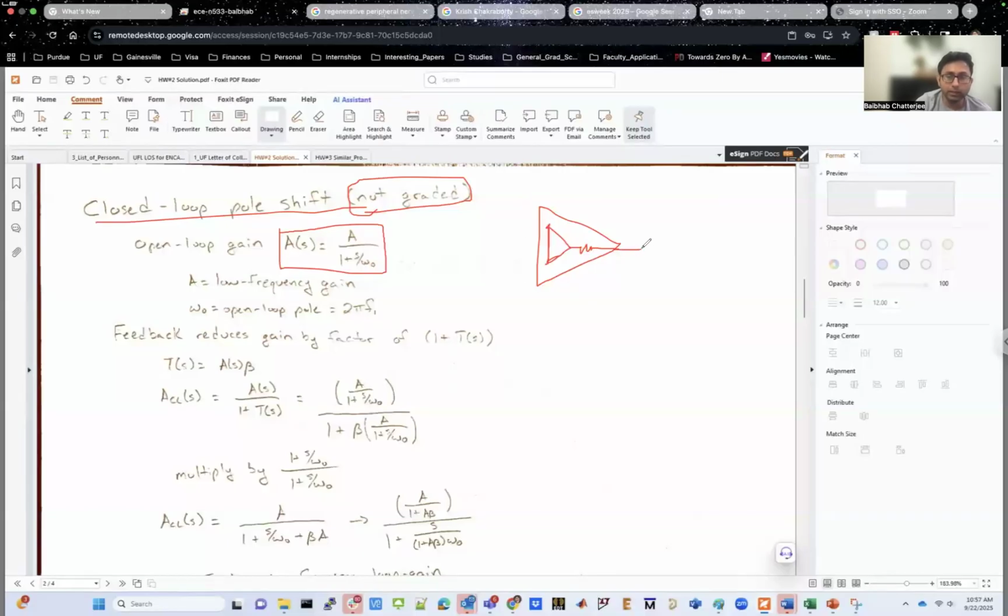So you have a resistance. And then, of course, for any circuit, at any point, you'll have a capacitance to ground. That's just the nature of circuits, that you always have a parasitic capacitance to ground at any point. Now, this RC network, a resistance in series and then a capacitance in parallel to ground, is a low-pass filter.